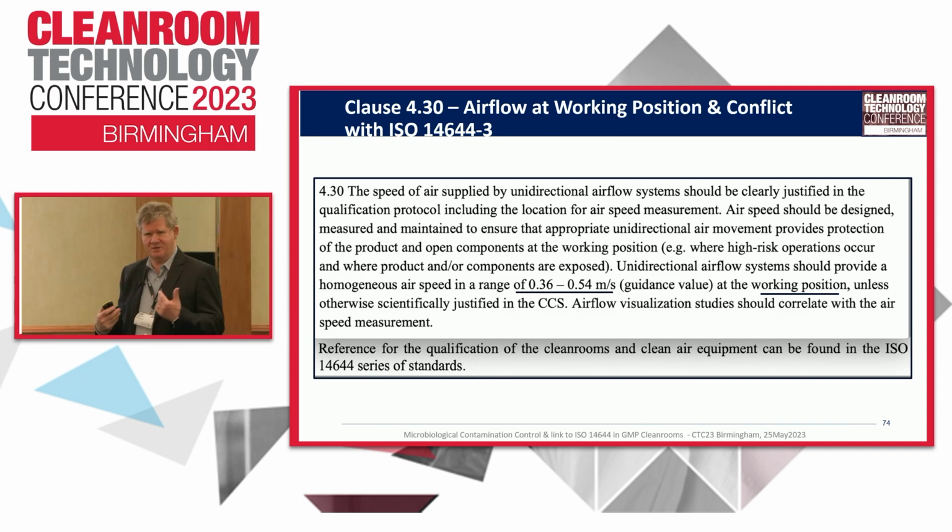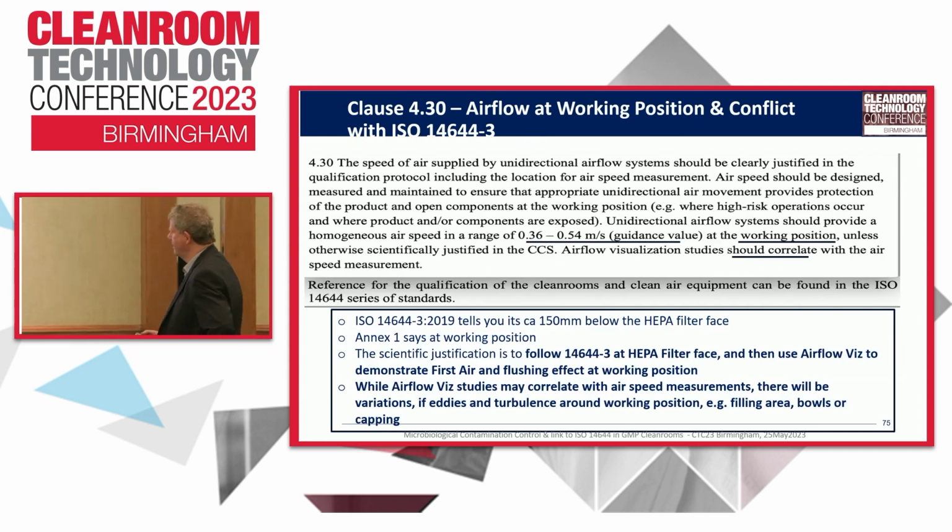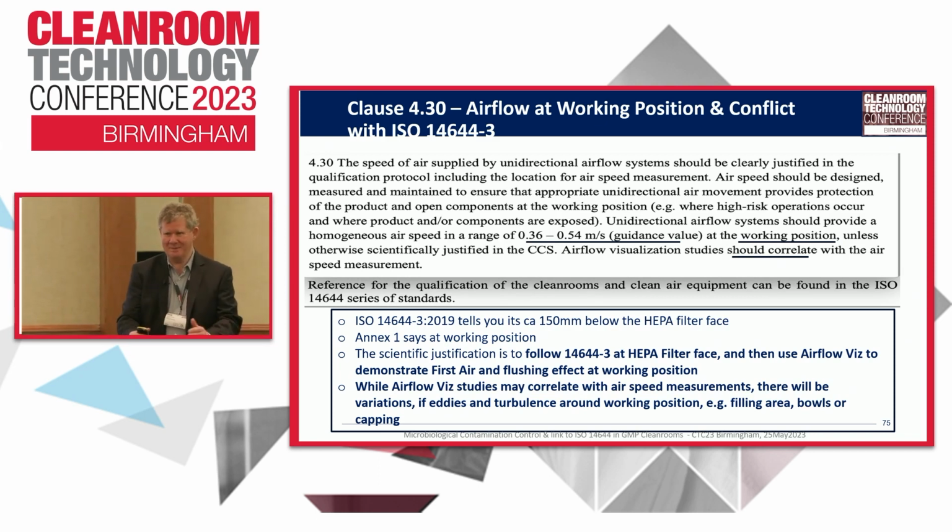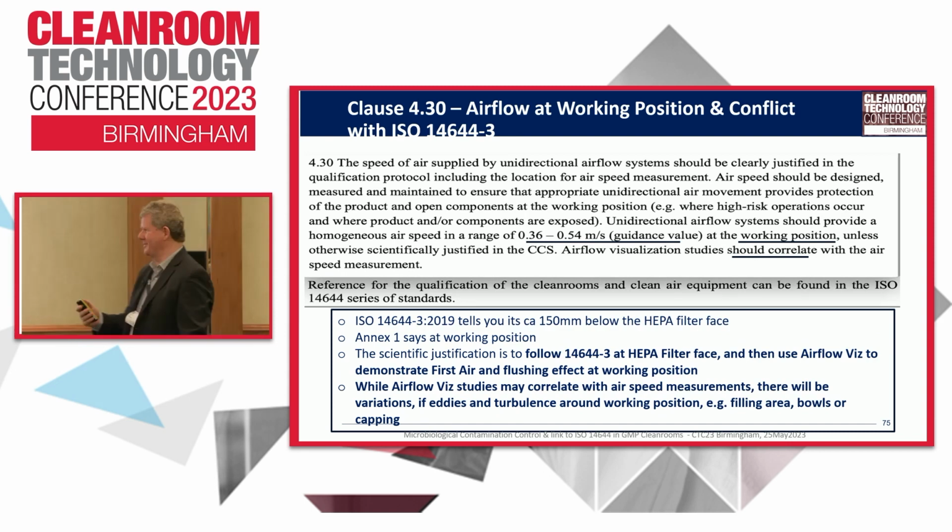Now again, you can see I'm a technical nerd. We do a deep dive into this stuff here, and this is just bad science. So the good news is, here's the answer. It's like I baked this cake beforehand. This is what it looks like when it's done right. So yes, you do your measurement below your filter face, your 6 inches, 150. So at the working position, you follow this and then use airflow visualization to demonstrate first air.